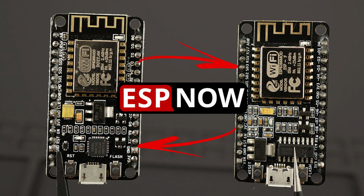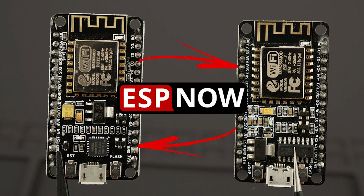So in this video, we're going to talk about a new protocol of ESP32 that is called ESP-NOW. In the past videos, we have discussed Wi-Fi and Bluetooth, but those protocols are designed for close range. But what if you want to communicate further? What if you want to communicate for a range around 500 meters to 900 meters? This is where a new protocol of ESP32 called ESP-NOW comes into the picture. This is designed to send a small amount of data for a longer range.